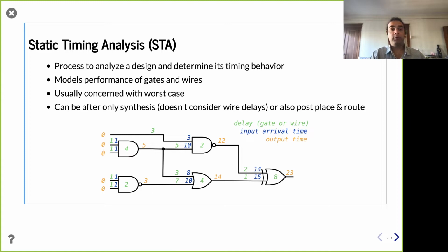It's just, from the point of view of what's the correct output, we believe that after 5 time units this gate should be outputting the correct thing, because perhaps it could be coming out sooner, but at least after 5 time units, because it came at time 0. We believe this wire can be traversed in 1 or less. This gate can be solved in 4 or less. So thus, this worst case scenario is this output's going to be ready after 5 time units, right?